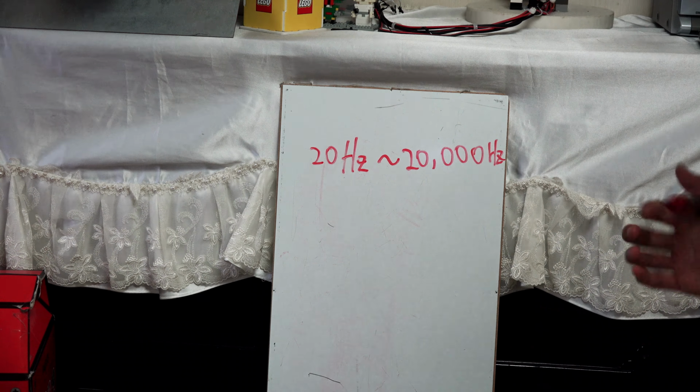You can write here the pin where you put the echo pin. It is just a number. You can write 8 or 9, or whichever pin you put the echo pin on, and high.